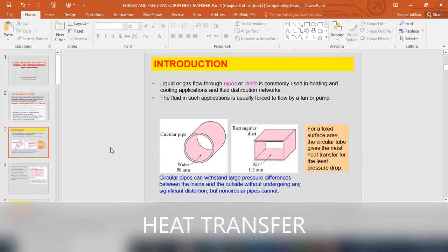We will also calculate that pressure drop, and we will include that pressure drop to size our pump. Our pump should be able to provide that pressure. It will increase the pressure constantly to compensate for that pressure drop.